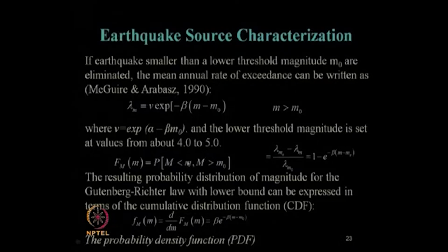If it is a very important structure, say bridge, say dam, etc., where we should go for deterministic seismic hazard analysis, but parallelly you can go for probabilistic seismic hazard analysis also in a logical way, but to select a threshold parameter say 4, like that. Okay? So, clear? So, this depends on the engineer's choice, engineer's experience.